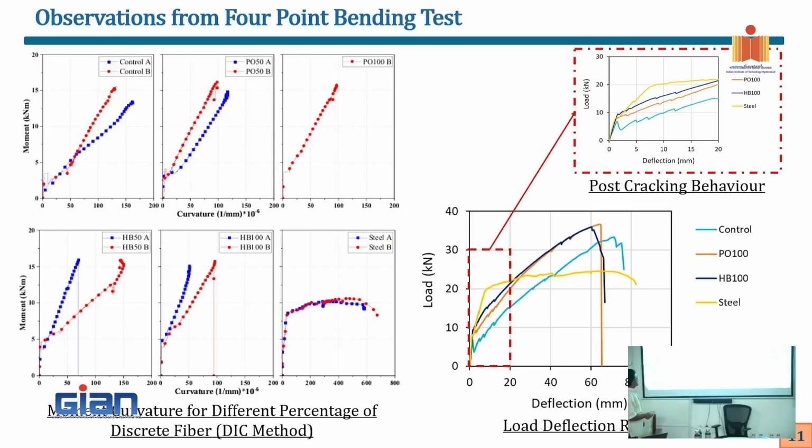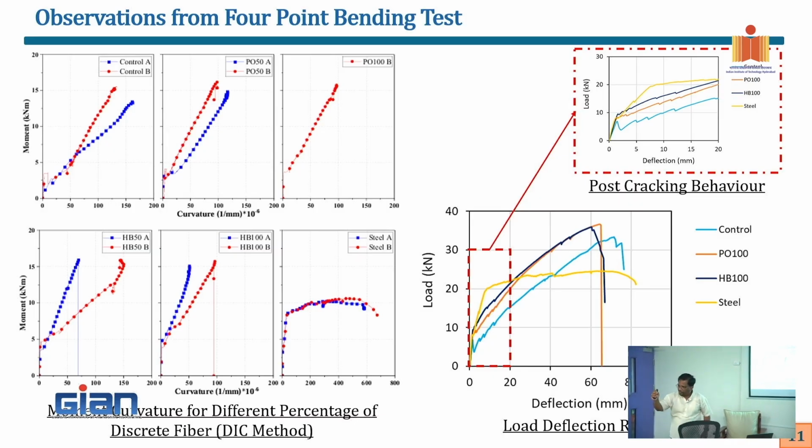So you see here now the I cracked. What I am doing is somewhere here, not exactly at ultimate, somewhere here, right? But this is the level at which I am calculating the I cracked. It is really cracked. But MCR is the moment which is causing the crack. At that time, the concrete is still contributing. That's why we calculate MCR. ICR doesn't correspond to the M cracking. It is corresponding to a moment which is much, much higher, but slightly lesser than M ultimate.